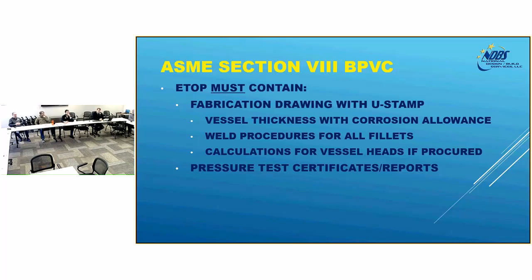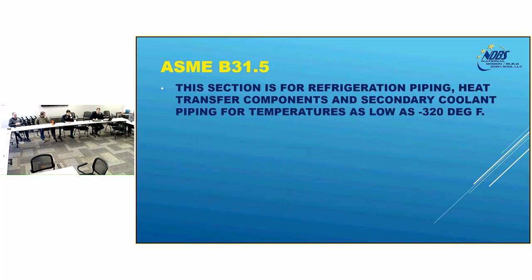You get into a lot of corrosion allowance calculations, and you have to get down to the details of how the welds are laid, what kind of weld it is, what weld procedure goes with that weld, if there's plates on the vessel that are welded on the vessel, how the end bells are taken care of. There's a lot of detail that goes into these. And of course, you have to have your certification. The PSVs themselves, which would be part of that separate training, are their own separate device that gets attached to protect the vessel. So I'll talk about that later.